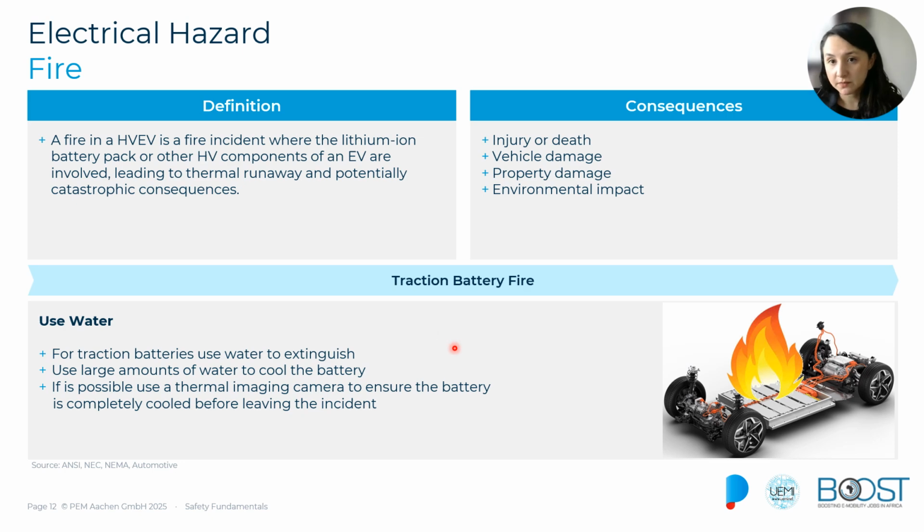For high voltage fires, for instance, what we have to do is to use a large amount of water, and that is what is recommended to cool down the battery. And always use, if possible, thermal imaging cameras to ensure that the fire is fully extinguished and that the battery is completely cool before leaving the scene and before assuming that it is already safe.